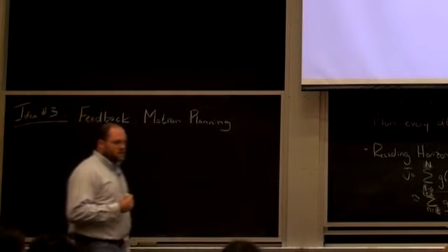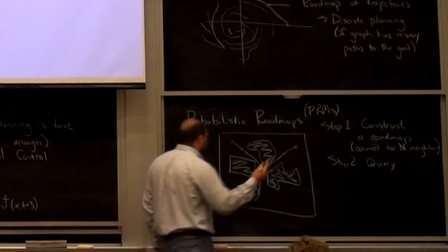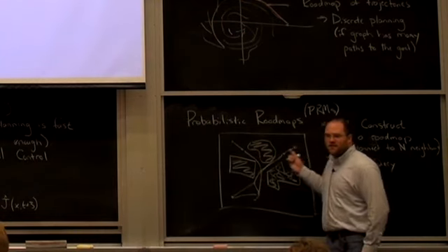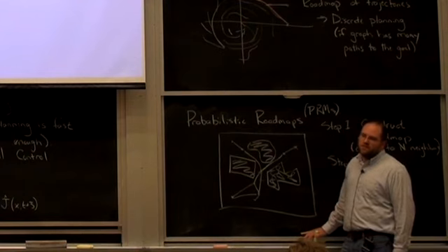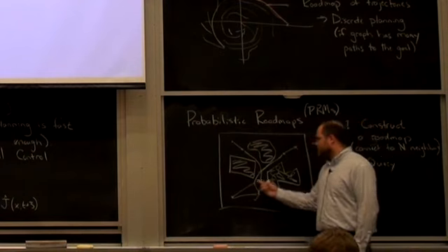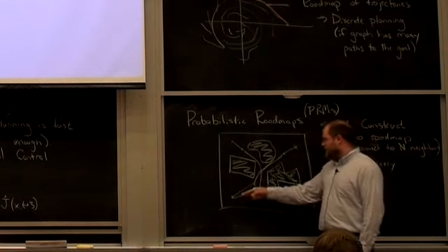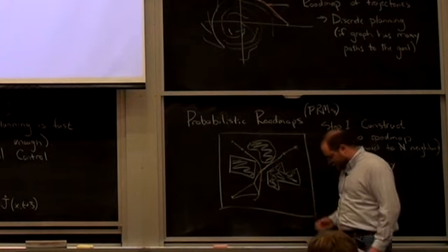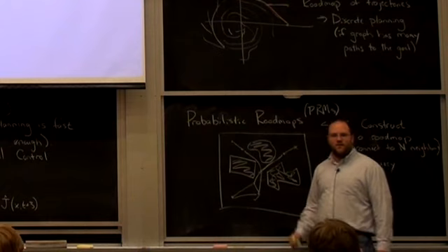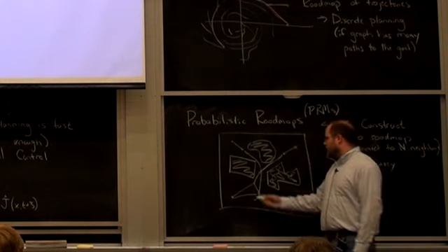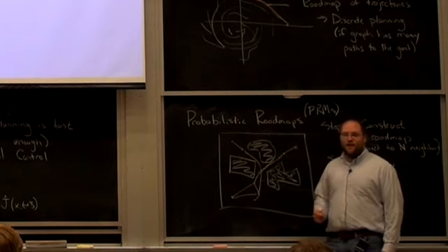So far we've talked about building some trajectory that we thought was good, and then afterwards going through and stabilizing it with feedback, right? That's not always the best recipe, because you could imagine, for instance, designing a controller that locally looked very good, but was completely unstabilizable, right? I say, perfect, my first stage of my control design, pick this trajectory, now I'm going to run LTV LQR on it to stabilize it, and then I find out, whoops, right there it's not controllable or something, right? My cost-to-go function blows up.